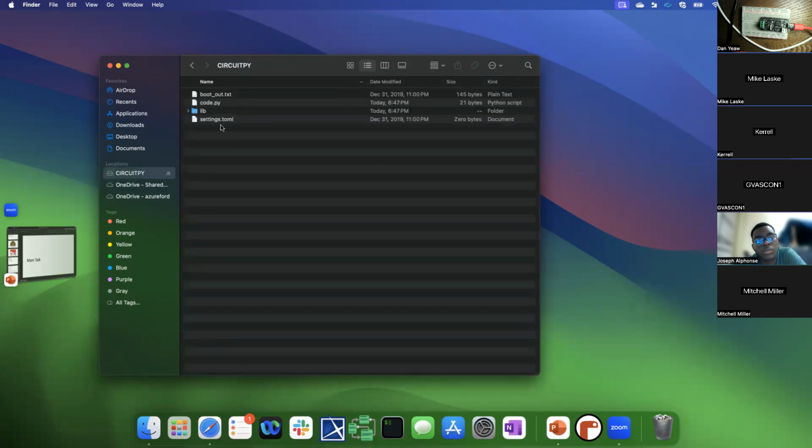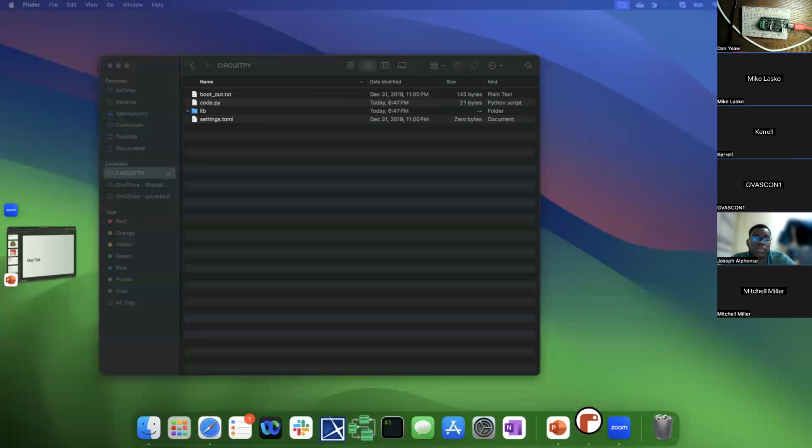You can see on here by default, there's a code.py. The board looks for that to run the program. It could also be called main.py or code.txt or main.txt. And then there's the lib folder, which is empty. That's where you'd put your libraries. So the main thing we're going to be using is this code.py. So congrats, we've installed CircuitPython. That was all there was to it. So we have this device running CircuitPython. I also installed Mu Editor, so I'll go ahead and launch that, and then we can start some basic coding for our examples for the demo.